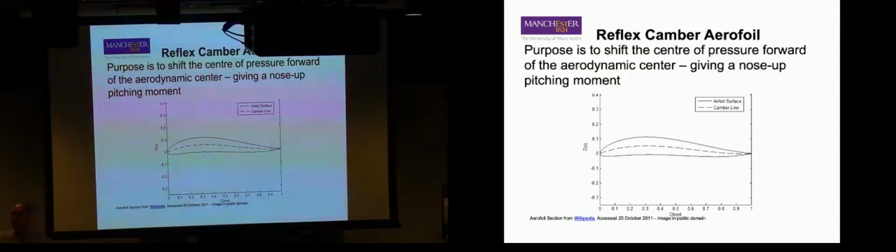So if you're looking at a flying wing like B-2 or a tailless aircraft, you'll often see a little bit of reflex in that trailing surface. Now, we might do it with a control surface with a tiny bit of deflection, or we may build it into the wing. But that's how we get rid of having a tail.